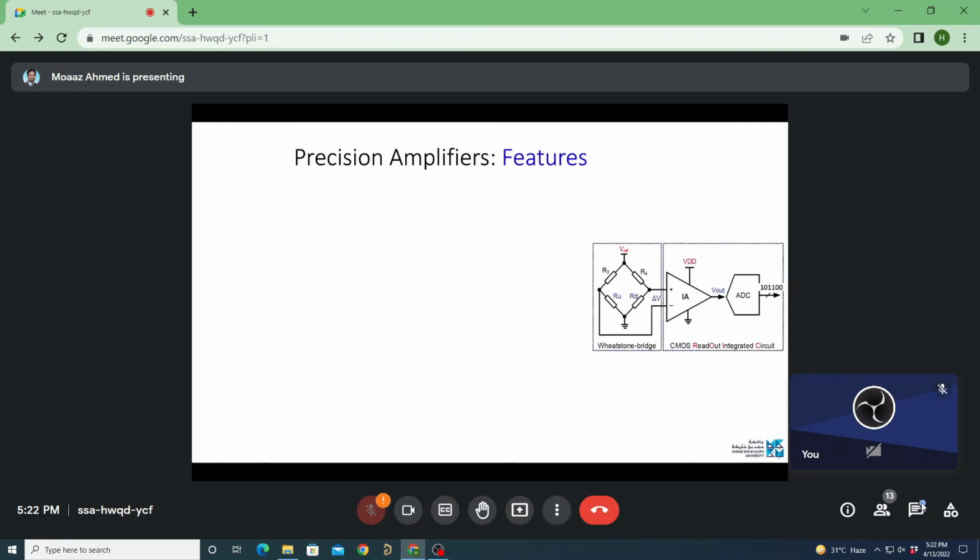So this is really one of the most fundamental blocks, and it looks challenging, but it's not. If you can design regular folded cascode amplifiers, then you just need to do a few more operations. With a set of switches, you need to do either auto-zeroing, or with a set of swapping switches, you need to do chopping. And then you will be amazed to see how powerful these two methods are. Simple but powerful. They will reduce your noise and offset to the microvolt level, which previously were in tens of millivolts.